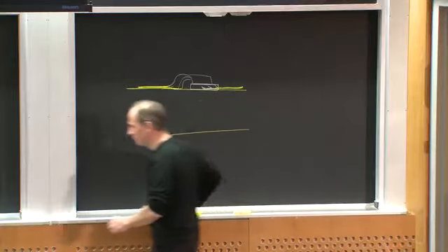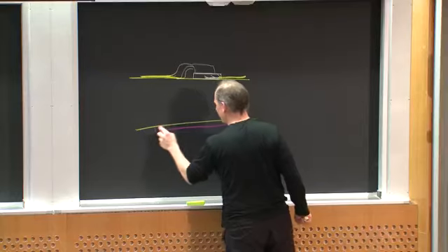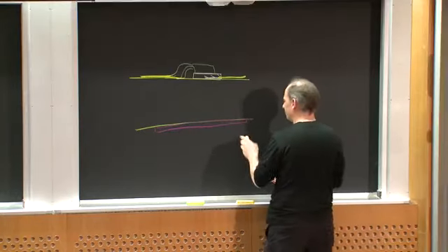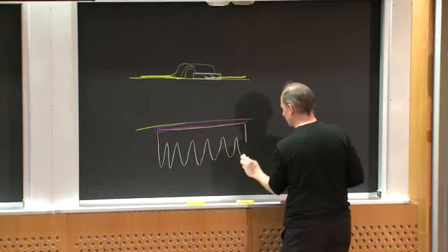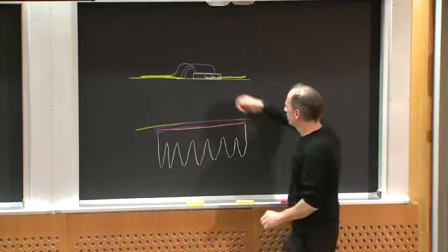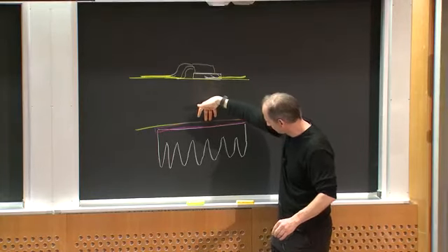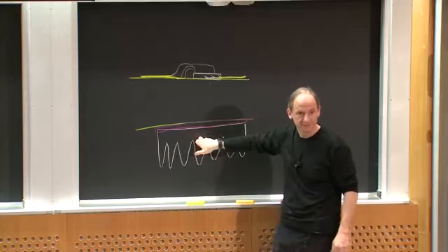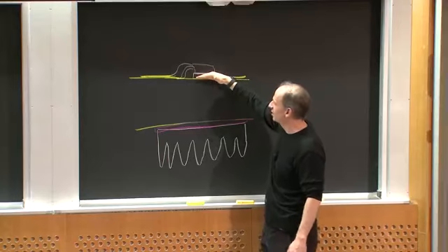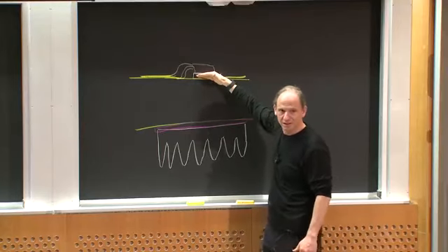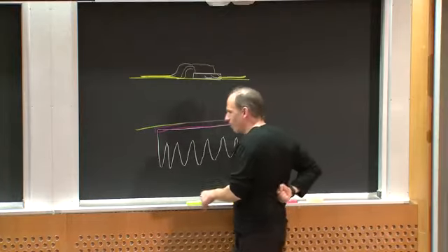So maybe on the other side of the board, I would put a thermal interface pad, and then a heatsink. The heatsink's mounted to the other side of the board. I'm going to try to get heat out of the device, through the package, through the board, through the interface material, into the heatsink. And this is necessary because you want to connect the device to the board for the electrical connection, which is the most important thing.